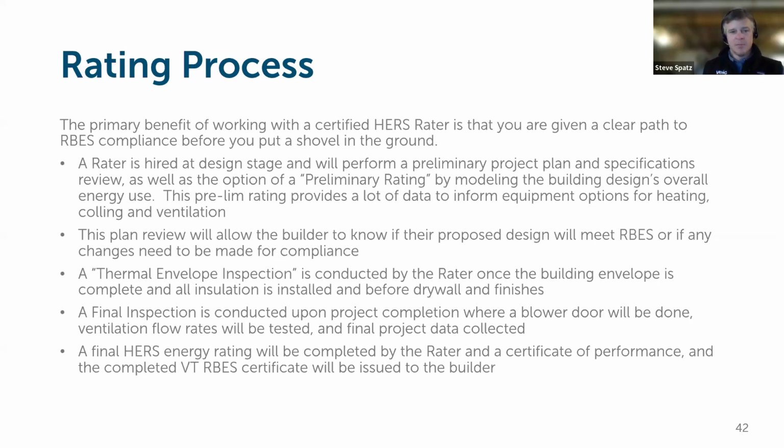So the thermal envelope inspection happens when the air barrier is complete, insulation is complete in the cavities, and before interior finishes go up. The rater is required to come out, take a look at that, verify everything has been done and done appropriately, verify R-values, and then the building can be finished.